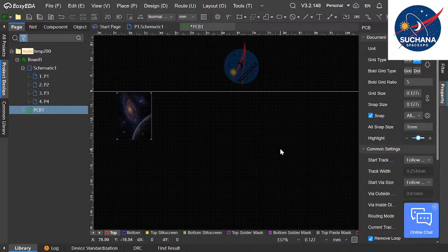After selecting the image, it will show you a menu. A menu would hover on the screen, and in that menu there will be a checkbox like place original image or not. If you want to place the original image, it refers to the colorful silk screen layer, where the image is colored. By default, if you do not enable the checkbox, it will be turned into a grayscale image or else a black and white image, right?